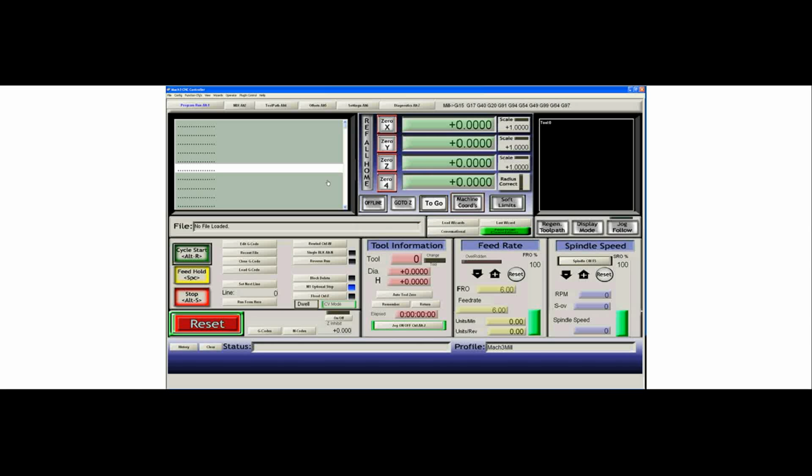If we now zero the X axis and jog a particular distance, you should be able to measure that, and it should have moved exactly 2.1877 in this case. That takes care of the two most common problems that you're going to come across in Mach 3 and the two most common reports of trouble.